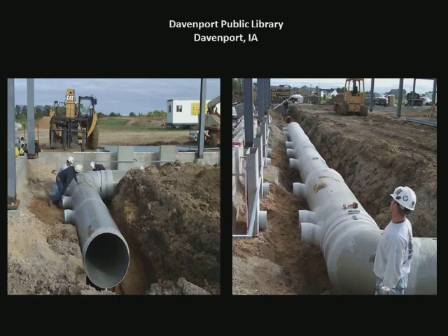This manifolding, like done with these boots, is a standard thing for us. We talked about it on this left image. We also have it on this right image. Here's that same joint held together temporarily by a metal brace that will be removed once the fiberglass joint is cured. So these 3 taps, this reducer, all the way down to here is our next joint.